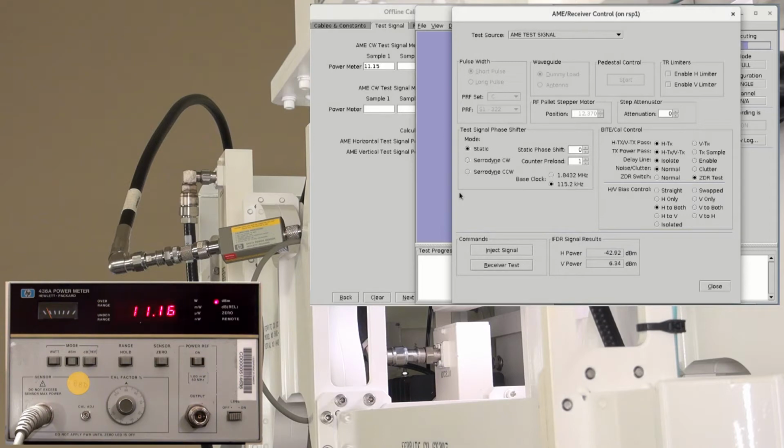If the expected test result is not met, replace the QN male adapter on the cable. If that does not resolve the issue, perform Fault Note 82. If Fault Note 82 passes and the ETR is still not met, replace cable 2W575.